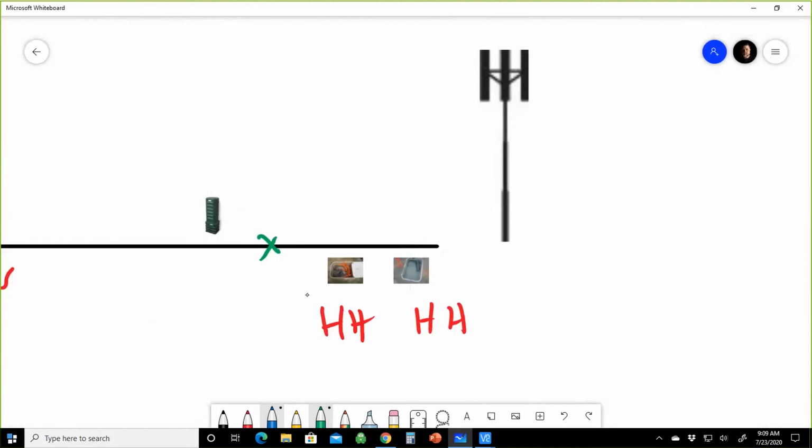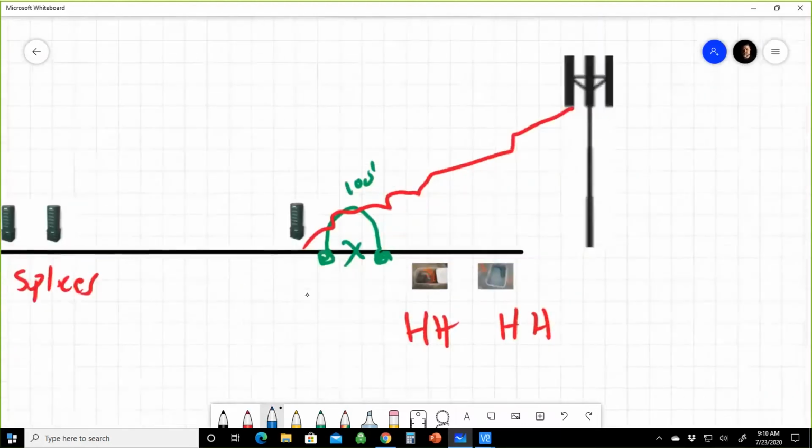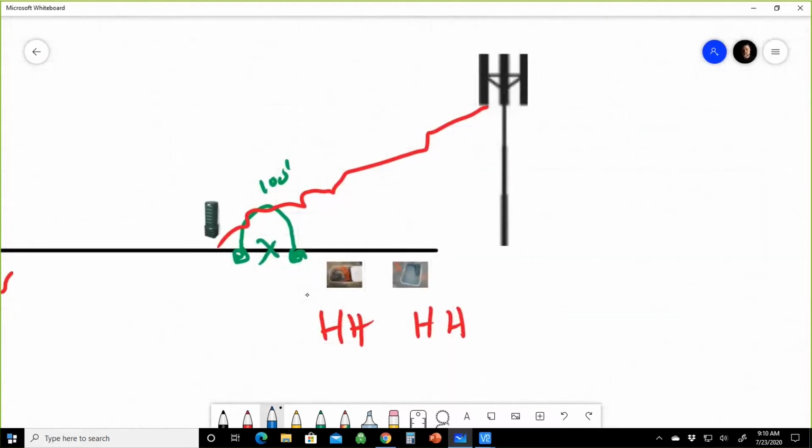And so what would happen is all of a sudden now we got this section of throw cable in here with two splices. You have one splice here, one splice here, and this is only 100 feet. Shooting an OTDR trace from the left, I could see both splices, right? I can measure both splices and see exactly what they are. But from the other direction, because it's so far away, we'll say 40 kilometers, it's going to come in and only see one splice.